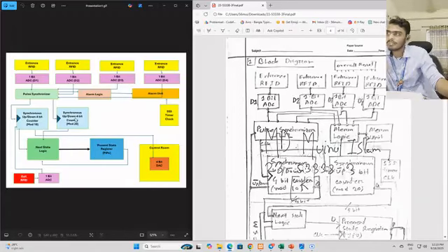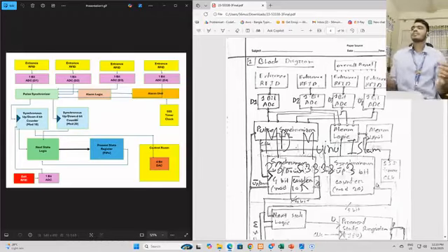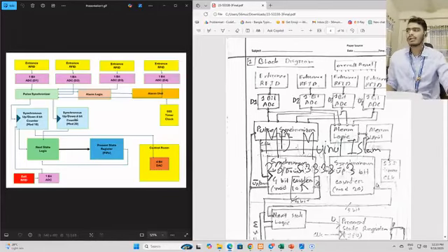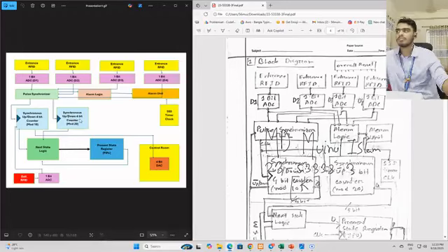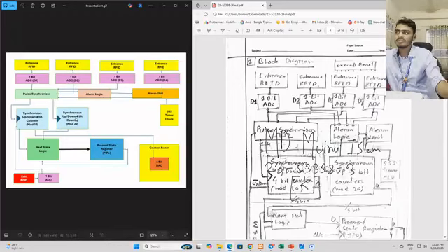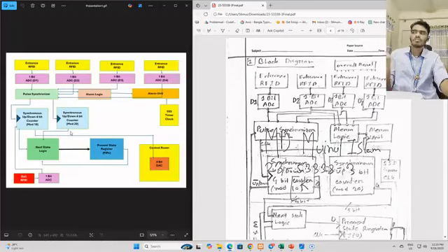This is a typo here, so it should be a 5-bit counter. I have added there 5-bit counter. So it's a 5-bit counter, and this counts the tickets which are being registered. Apparently if you have a ticket, you will go through the entrance. If you go through the entrance, this will count. And this is not an up down 4-bit counter, this is a typo as I copied it from this one. This is basically an up counter. I have added it here. So a synchronous up counter, and this is a 5-bit up counter and mod 20. So this counter tracks each of the entrances and counts upward. It doesn't connect it.